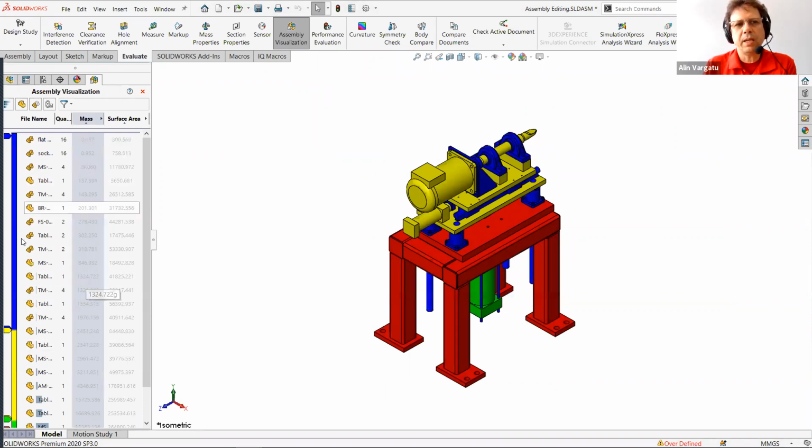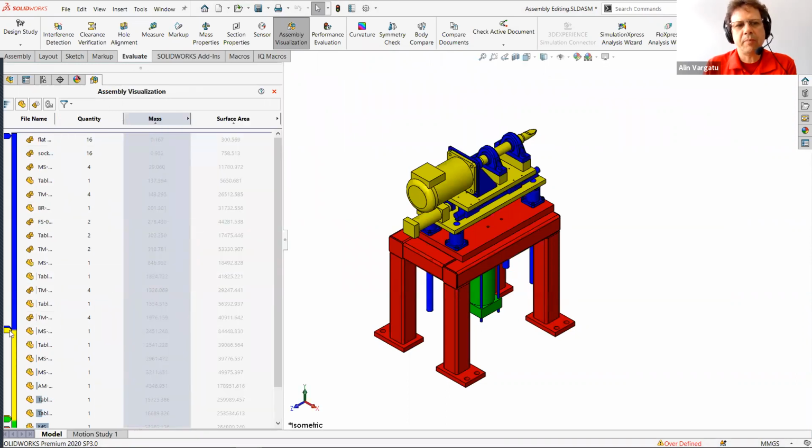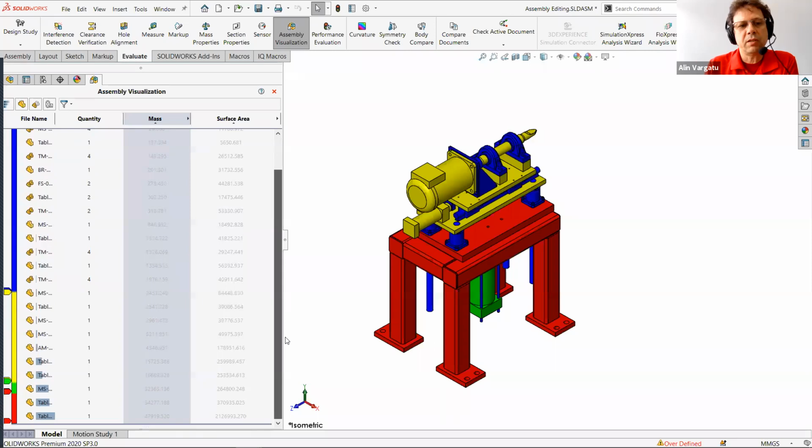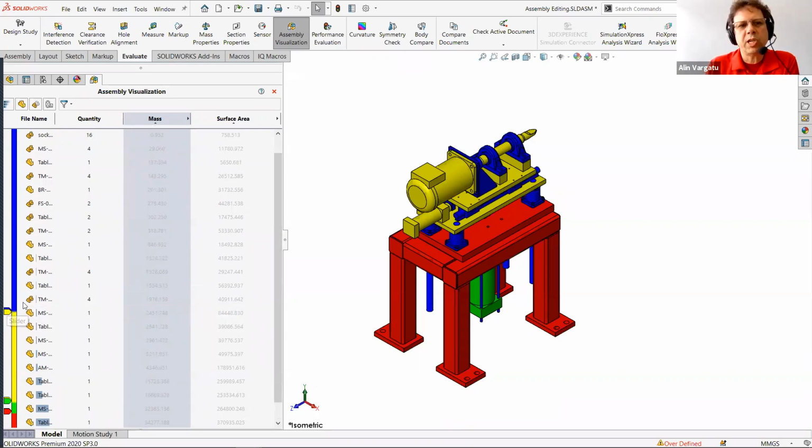The only thing to be aware of here is that the values assigned to the sliders are not going like what we had before, 0 to 100 grams, 100 to 500, and so on and so forth. SOLIDWORKS is simply going to pick the intervals weighted on the number of components that you have here. So the only thing you might need to do is a bit of adjustment.